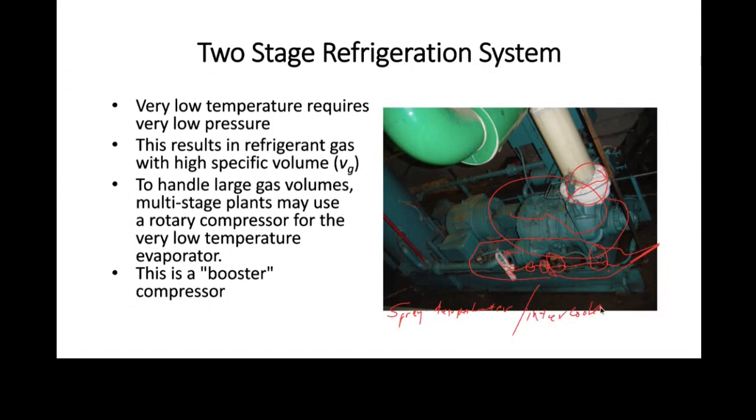Okay, and that's where we're spraying it in, and then that's actually the discharge. And if we overfeed too much, like if we put too much liquid in there, we shouldn't because we've got a thermostatic expansion valve. But if we do put too much, the liquid will go into this vessel, which is like a separator vessel.